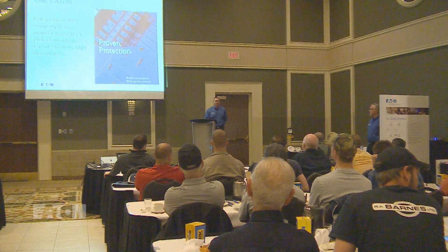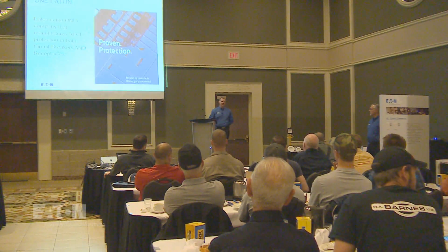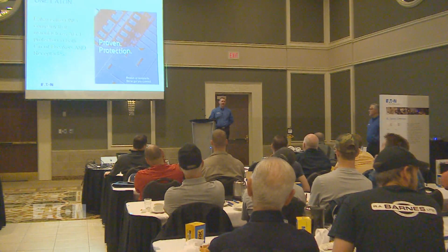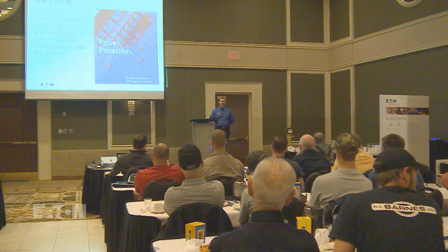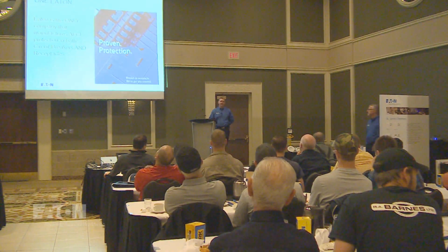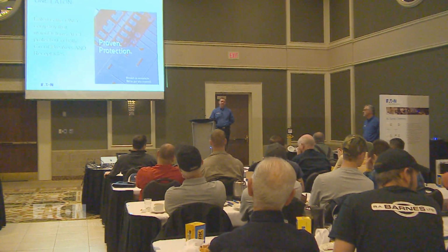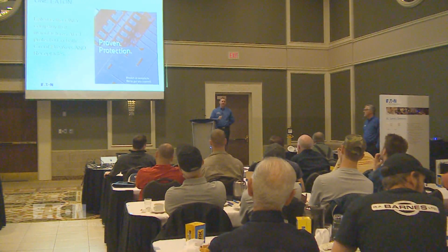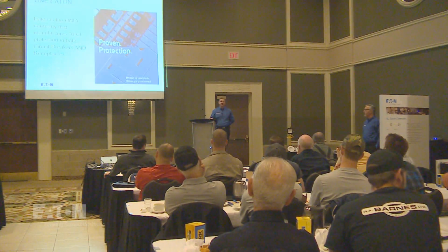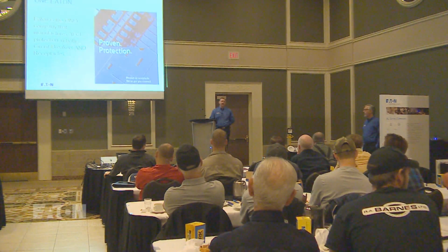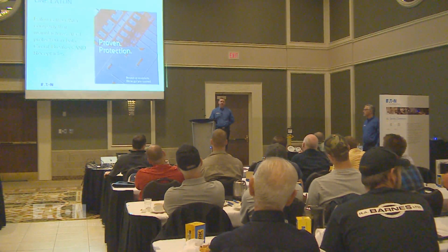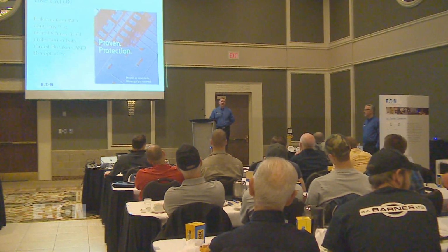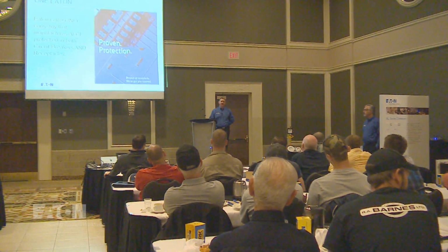Even when we introduced the branch circuit a while ago, it changed the technology and the breakers got smarter. The arc fault testers on the market didn't keep up with that technology, and the latest arc fault breakers didn't recognize the tester as a true arc, because it's not a true arc, it's just a test indicator. So right now, as far as I know, there are no AFCI testers on the market that will be compatible with this technology. So the only way to test it is to press that test button.